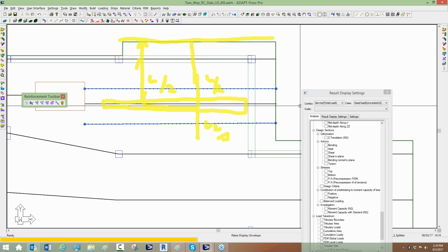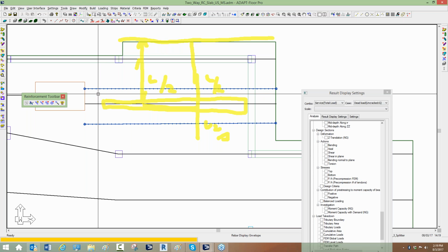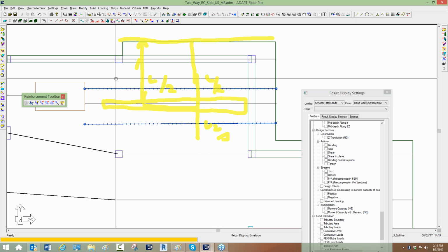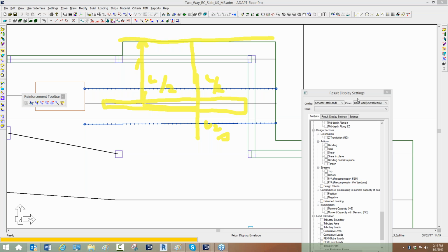We're going to introduce in 2018, hopefully, a beam manager which allows the user to modify the flange width more easily versus actually graphically having to modify it, where you can enter values for the flange width and the program designs based on that beam manager input versus the graphical input.